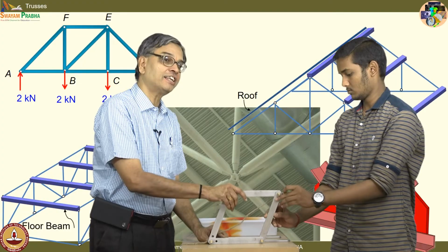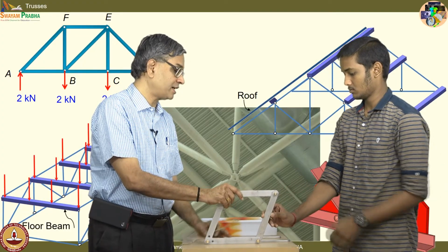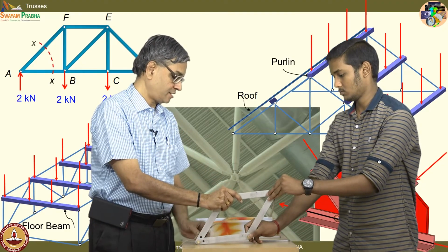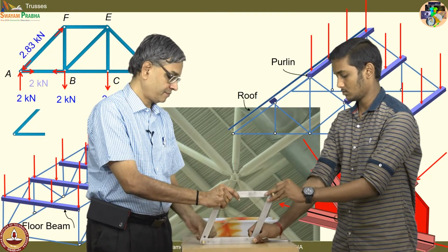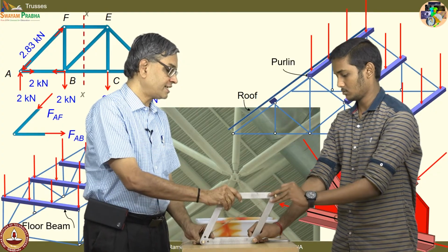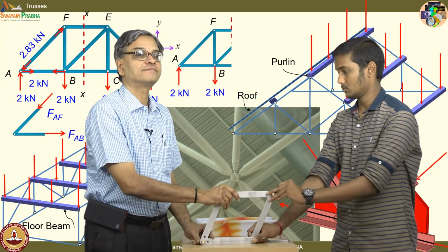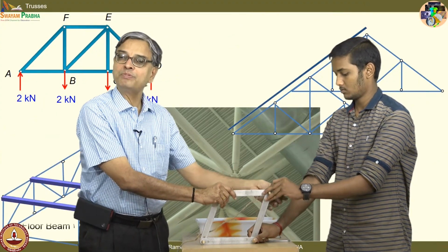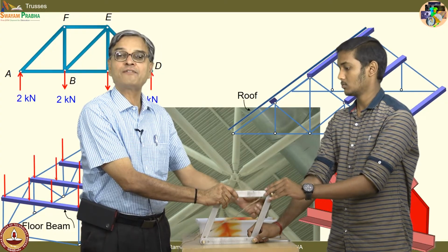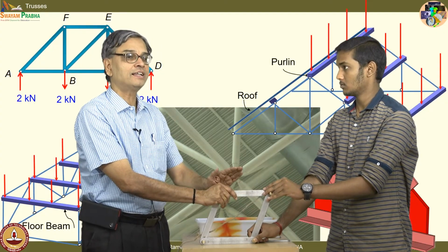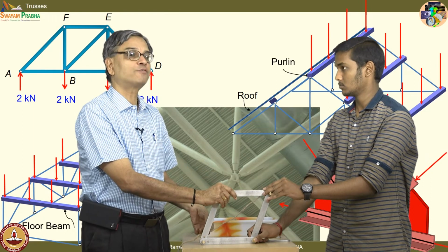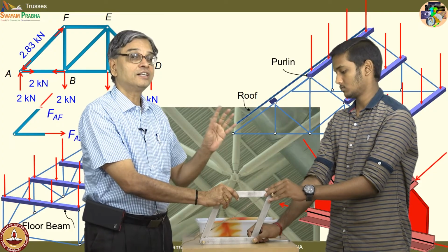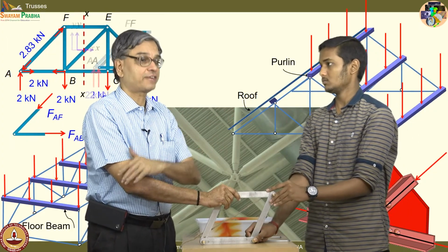So, what you have is two members like this, which takes care of wind forces in any direction. So, the cross bracing is always thinner than the actual member. Even a simple string can do the job. I can have a metallic wire which will replace the thick bar which I have used earlier, as long as I am interested in arresting the effect of wind.